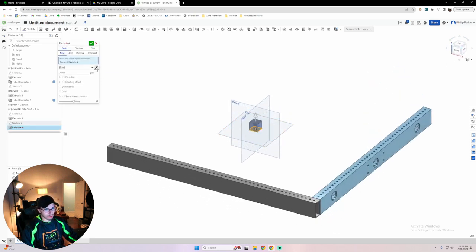The reason we extrude it down is because we want the reference cube to signify the ground as well. So we want it below the lowest plane. We're also going to go over here, and in this top dialog box, we can click the pencil button and write what this feature is.